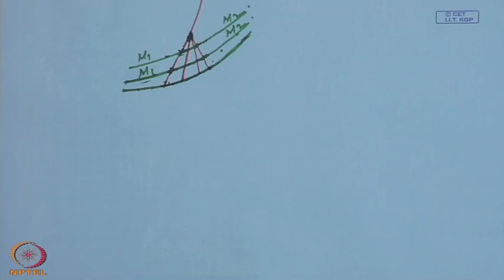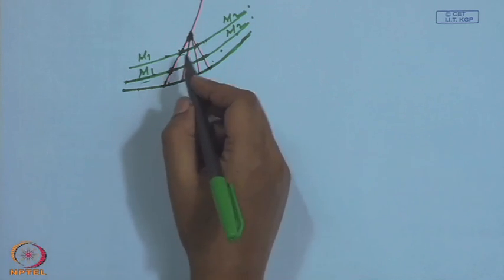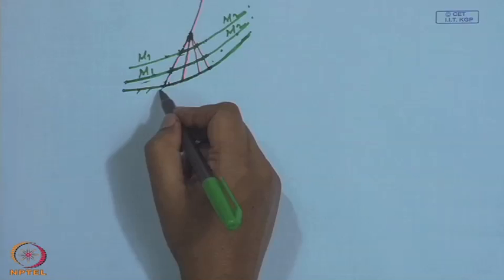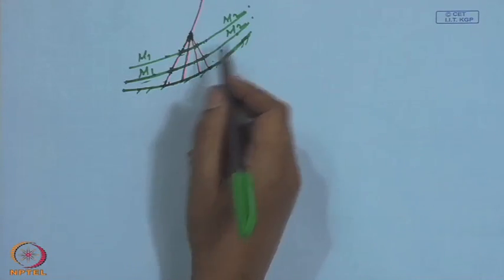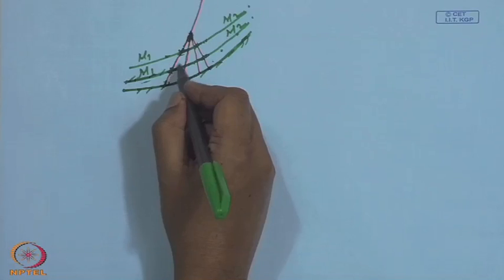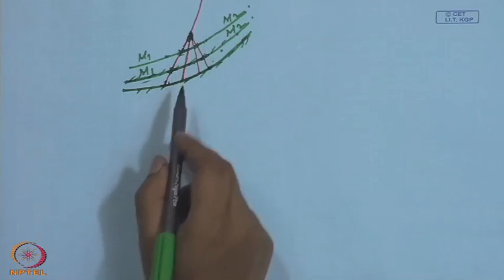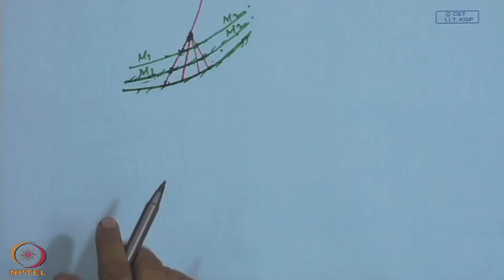Now, again let us say that if we have made this wall, this is also a wall, and replace this streamline is also by a wall, then between these two walls there will be an isentropic compression, and because the gradients will always remain smaller, the compression process will remain isentropic without having a single stronger shock.